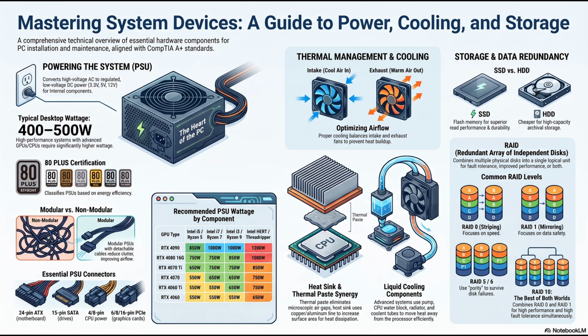Still using thermal paste, I assume? Always. But inside this water block, instead of fins reaching up into the air, there is a dense labyrinth of microscopic copper channels. Like capillaries. Precisely. Next, you integrate a mechanical pump into the system. The pump acts as the heart, continuously forcing liquid coolant through a network of flexible tubes.